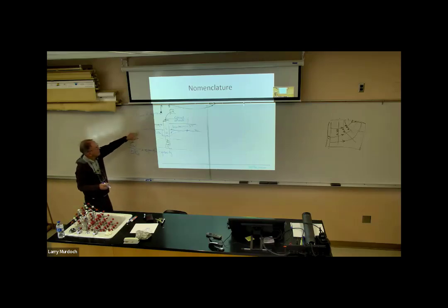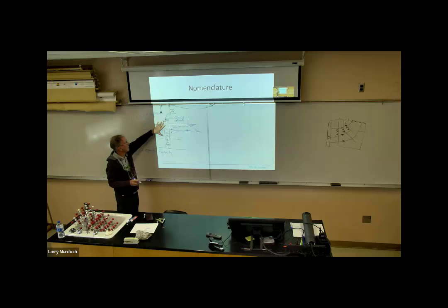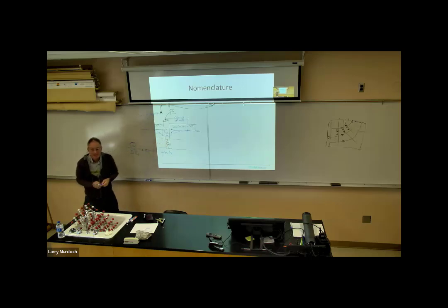Another combination of terms that we're going to be interested in is how much power do we have to have? How the drawdown is different from the drawdown in the well, because they have different notation, delta P and delta PW. Delta P is the drawdown anywhere. And delta PW is just the drawdown in the well, specifically at that location.